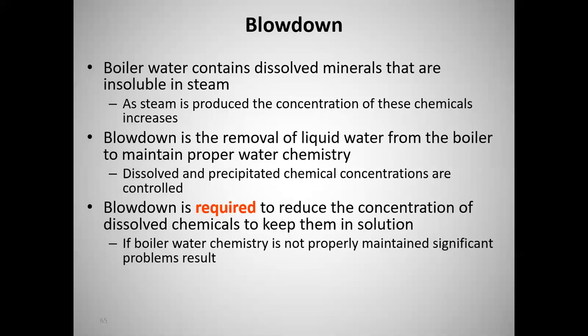So blowdown is the removal of liquid water from the boiler to maintain proper water chemistry. Dissolved and precipitated chemical concentrations are controlled. Blowdown is required to reduce the concentration of dissolved chemicals and keep them in solution. If boiler water chemistry is not properly maintained, significant problems